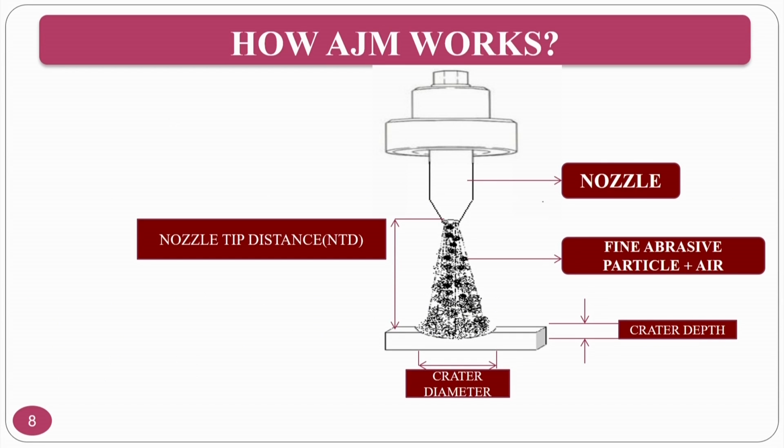If you see here how abrasive jet machining works, this is the nozzle. This is the nozzle tip distance, this is my workpiece, and the distance between the workpiece top surface and the nozzle exit is the nozzle tip distance.